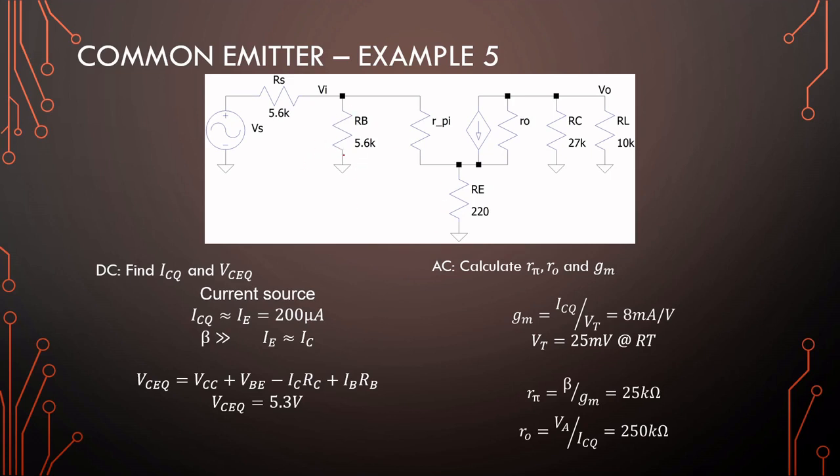And using a current source makes it easier for us to choose almost any base resistor here. And RC's choice can match up with R load. So if you need to build an amplifier that has input matching and output matching, the one with a current source is almost ideal. And even with RE, you can select the gain that you want.